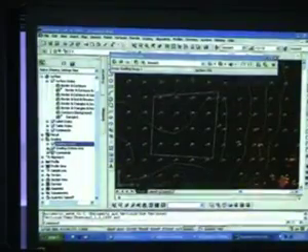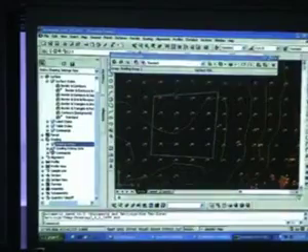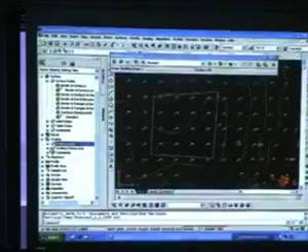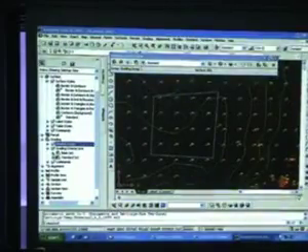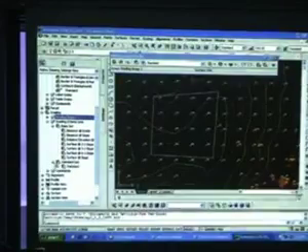But sometimes, of course, if it's daylight, you want the cut or fill from the platform to go all the way up or down until it finds the original ground. In some cases, you may want them to go down to a particular set elevation, maybe to an absolute elevation of 30, for example, or you want a relative distance of maybe 1 meter, something like that. So this is what the grading criteria set is for. It holds all that kind of information. So these are some of the sets that we have.